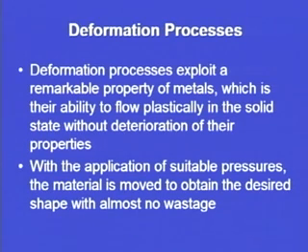So, what are basically deformation processes? Deformation processes exploit a remarkable property of metals. What is this remarkable property? It is their ability to flow plastically in the solid state without deterioration of their properties. Metals can flow plastically without substantial change in their properties. So, these deformation processes make use of this property of the metal.